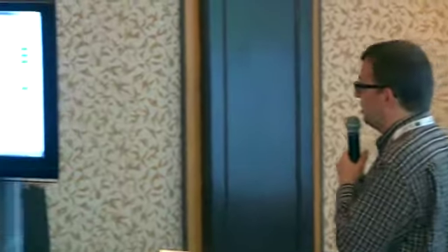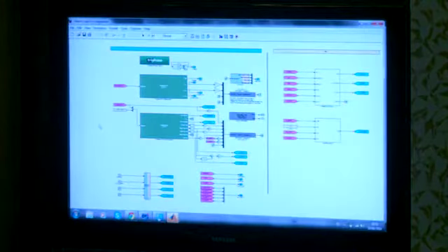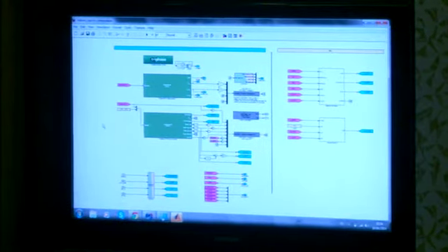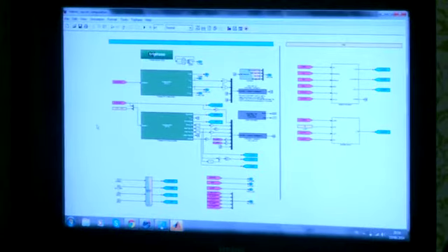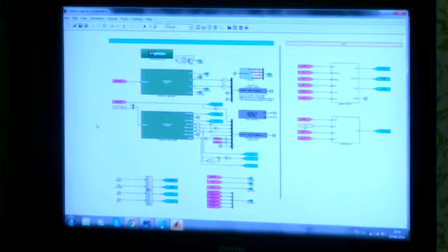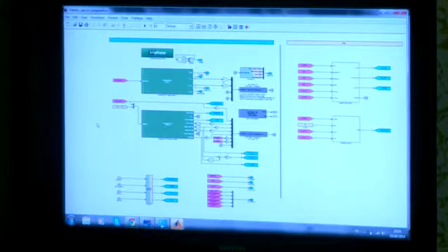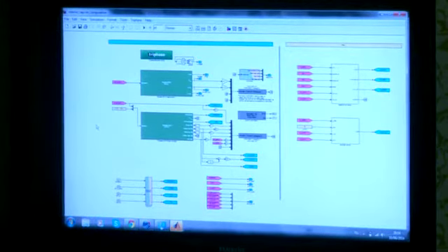The green blocks have everything to do with managing the EtherCAT master on one hand, and retrieving the I/O that comes from the measurements and the amplifier. If you look at the setup, there are actually 3 components. There is the OPAL-RT unit, which is the real-time simulator and also part of the amplifier controller.